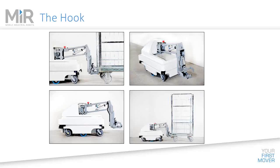So that if I don't have a cart behind this robot, that hook assembly is locked directly behind, as you see it in this upper right hand picture, so that as I turn around corners, that hook assembly doesn't slide out and hit a wall or somebody. So it's locked in place right here. But as I pick up a cart and clamp it appropriately, then I release that brake system and allow that cart to follow the robot as it's moving from point to point. You'll see that as it drops a cart, the last thing it does before it releases that cart is to square up with that hook assembly so that when it's moving without a cart, it is locked directly behind it.